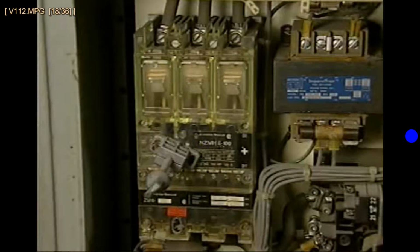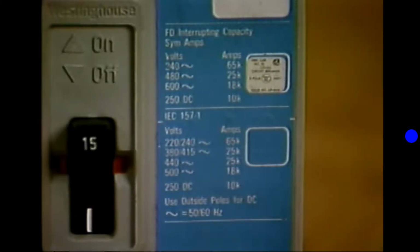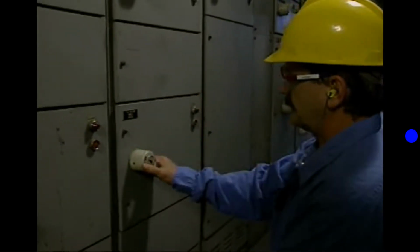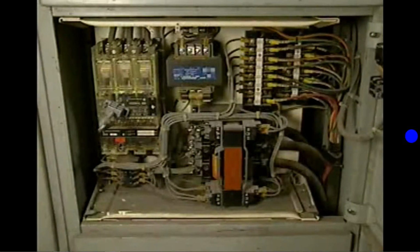The highest current at rated voltage that a breaker is designed to interrupt is referred to as the circuit breaker's interrupting capacity. The interrupting capacity of a molded case circuit breaker is usually marked on the breaker's casing. Now, the current value at rated voltage at which a circuit breaker interrupts current flow, or trips, is called its trip point. Many circuit breakers are designed to carry a specific amount of current without tripping. There are also some circuit breakers whose trip points can be adjusted.